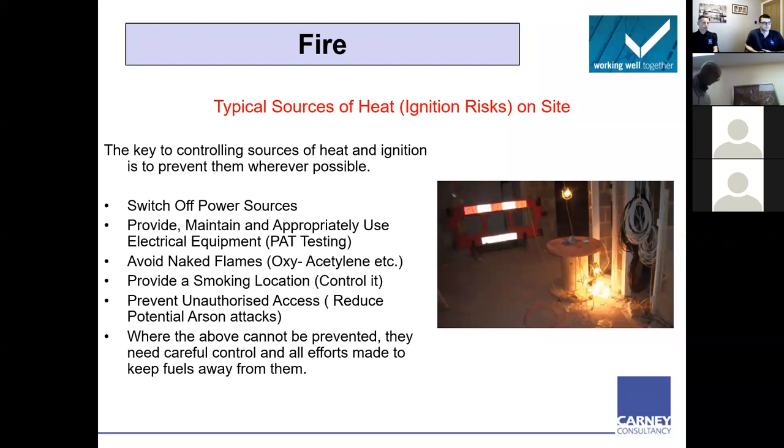Avoiding naked flames, so things like oxyacetylene, welding on site. Again, sometimes it needs to happen. However, if it is happening, what are we doing to control it? But in the first instance, you should be thinking, can we actually avoid it? Can we avoid welding on site? Sometimes you can, sometimes you can't.